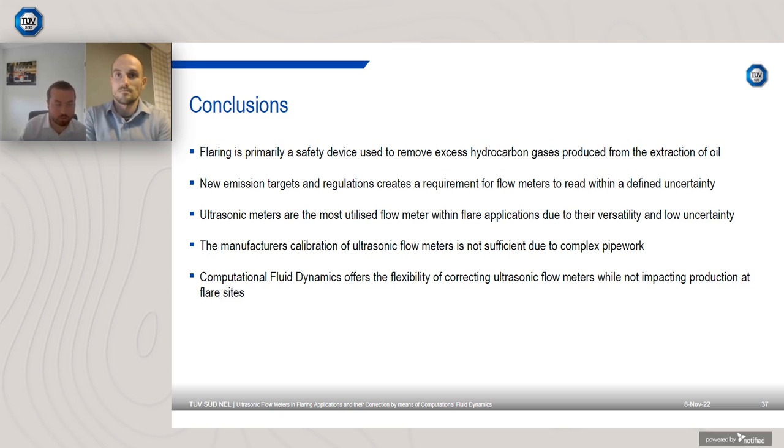So at higher Reynolds numbers, you'll likely have persisting swirling flow, and the flow profile will pretty much not always be fully developed. So the message here is even if the manufacturer's recommendations are respected, you still really need to calibrate your meter to see what effects the disturbed flow has on the meter. Hopefully that answers that question.